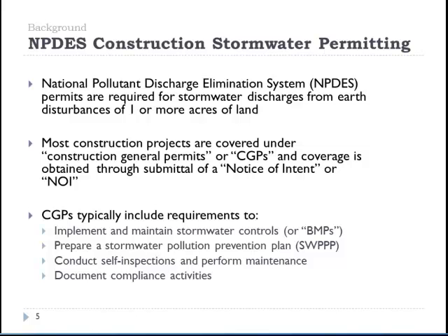Permits are also required for those smaller disturbances that are part of a common plan of development or sale, typically in a residential type of project where those add up to more than 1 acre. Those would also require permit coverage.